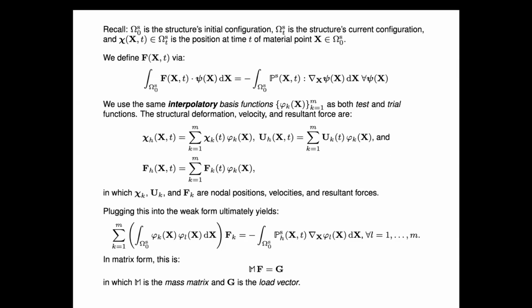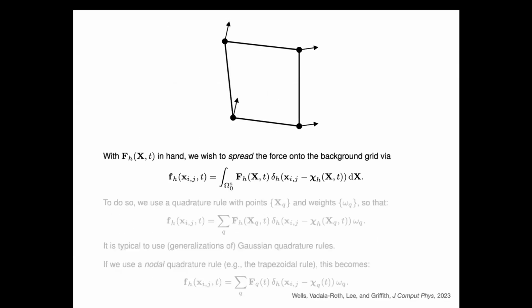I want to make sure it's clear. We're solving for the nodal forces, but you can evaluate those nodal forces anywhere in the solid region because you have these interpolatory basis functions. So one of the things that we started doing when we first put this together was to interpolate the forces to arbitrary positions within elements. Because at the end of the day, we want to take this Lagrangian description of the elastic force density and turn it into an Eulerian description of the elastic force density. And to do that, we need to compute these integrals of Lagrangian forces times regularized delta functions.